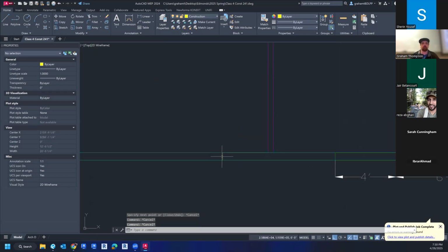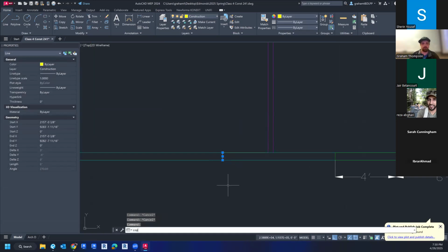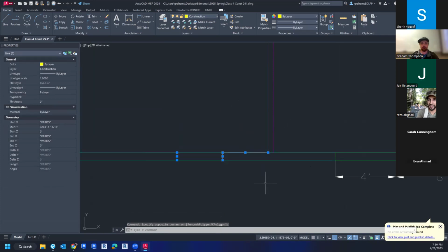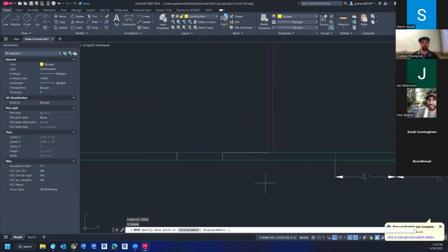And then I know that I want my door to be, it's an exterior door, so I want this to be a 3-foot door as well. And just because I want to give it a little bit more room for clearance when that door opens up, so in case it swings all the way back, I'm going to move this over like 6 inches. All right.